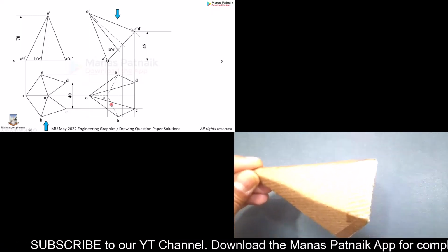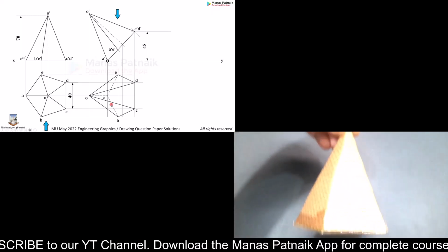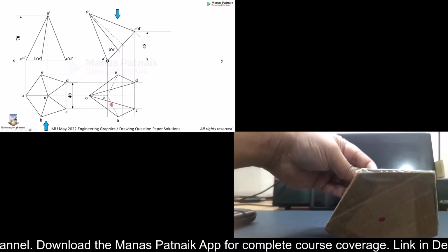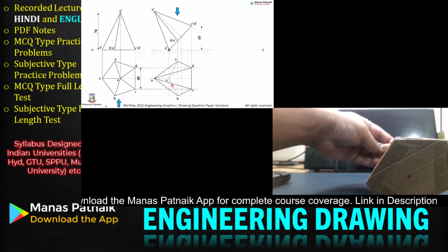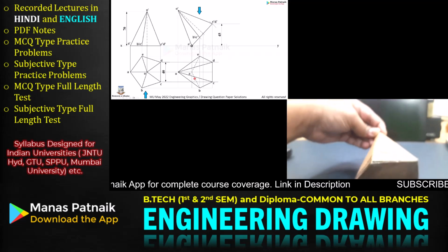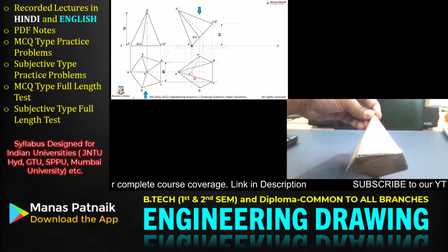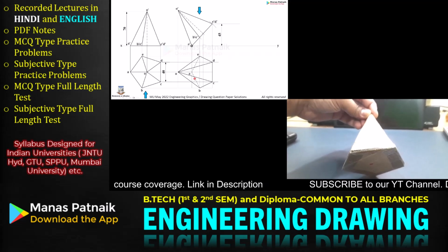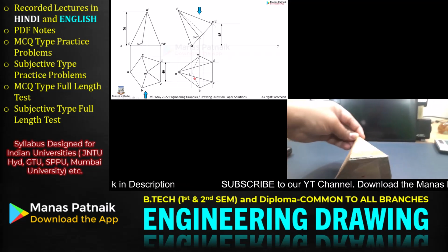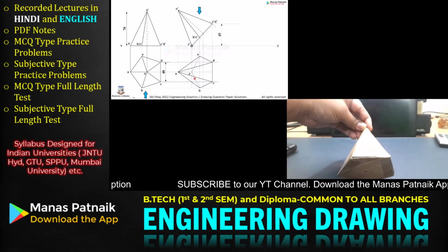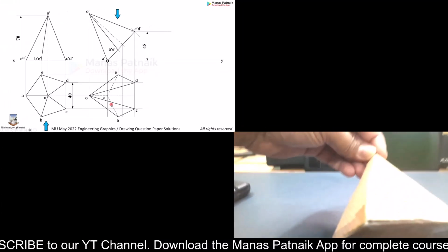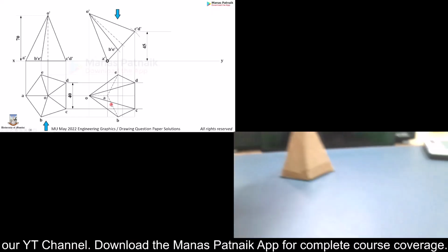Now we are going to rotate this, and now you can see this edge over here. This edge becomes now parallel to the vertical plane. The vertical plane is here. My writing pad is the vertical plane. So in this condition, you need to make the final front and the final top view. Now step 2, rotate it by 90 degree in the clockwise sense. For step 3, making this edge parallel to the vertical plane. Let's do it. Here we go.